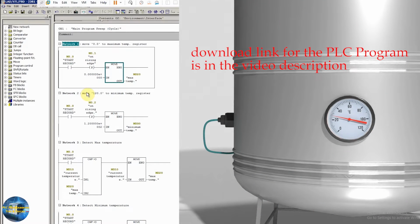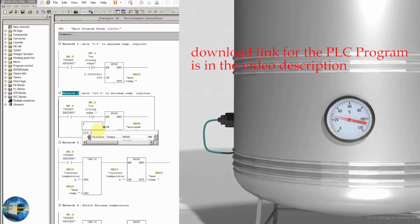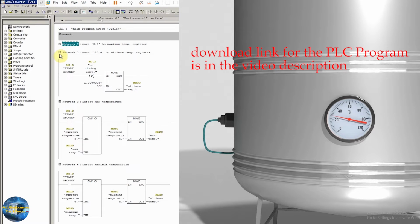In network number 2, we will move 120.0 to the minimum temperature data register. In a similar way, whenever the M0.0 start record bit is on, on the rising edge, we have a move command. It will move 120.0, the maximum temperature range of the temperature transmitter that we are using today. This move command will transfer 120.0 degrees into the MD30 minimum temperature data register, and this data register will be keeping the record for the minimum temperature value. So we will close our network 1 and network 2.